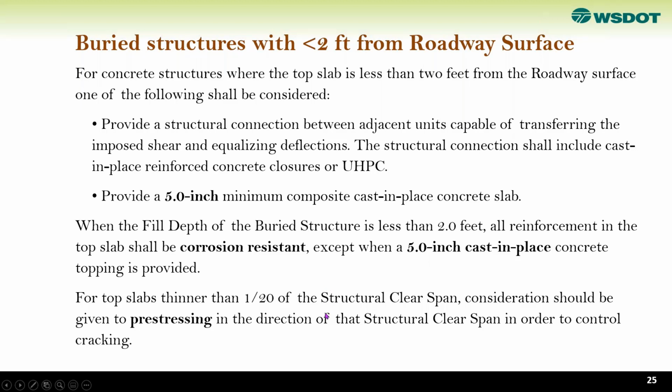And also if we have a thinner slab, as the slab is getting longer, and if the thickness of the slab is 1/20 of the structural clearance span, then we do require pre-stressing on top of the slab.